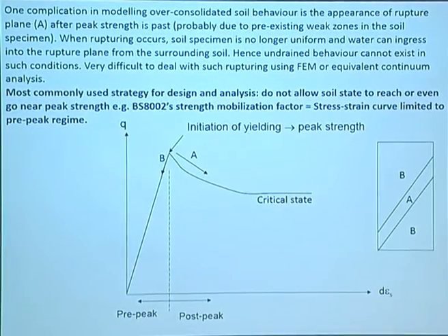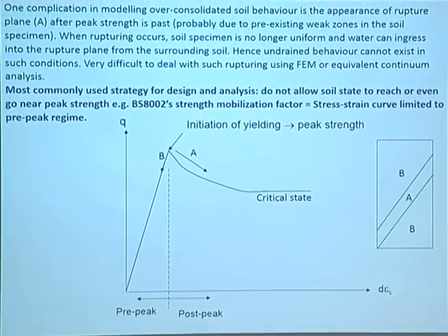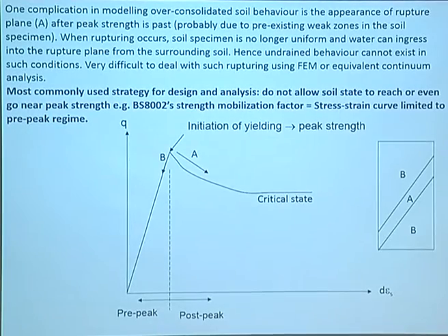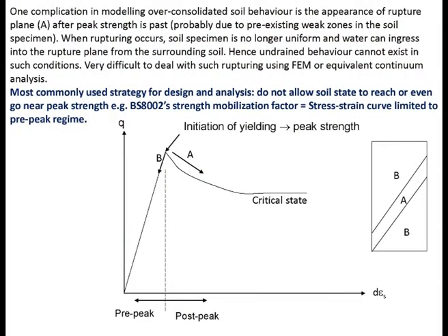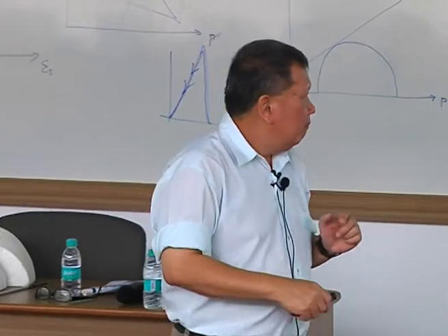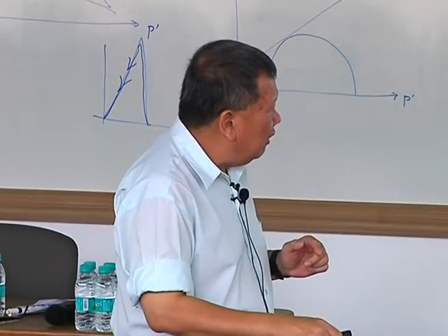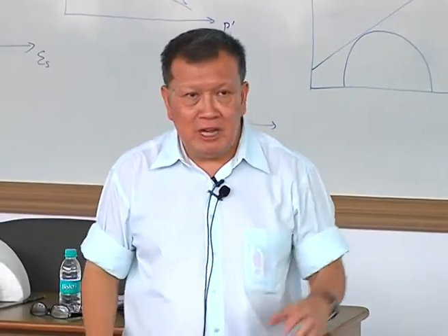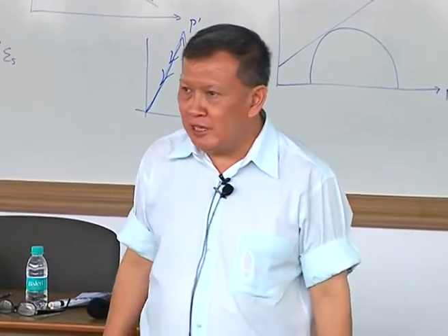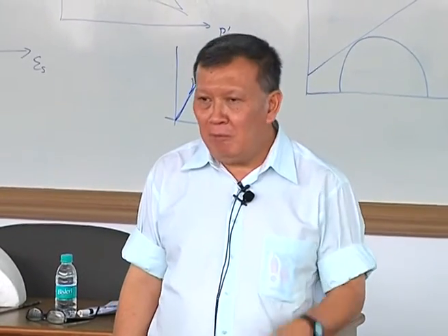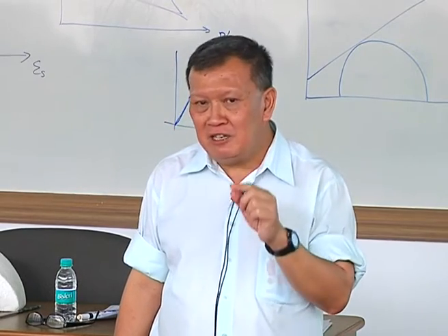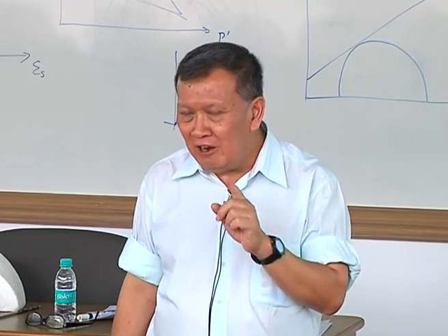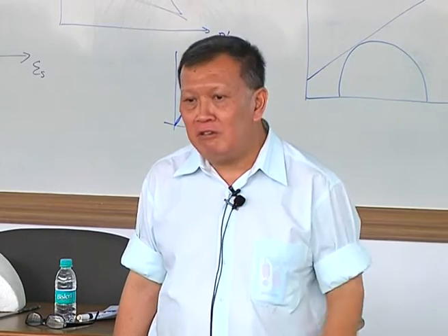Okay? Now, the difficult thing with controlling this is, because your shear band is relatively thin, it is very hard to keep your shear band undrained, because your shear band can easily suck in water from the surrounding region. So you can turn off all the valves to the sample if you like, but you cannot prevent water from flowing into the shear band.